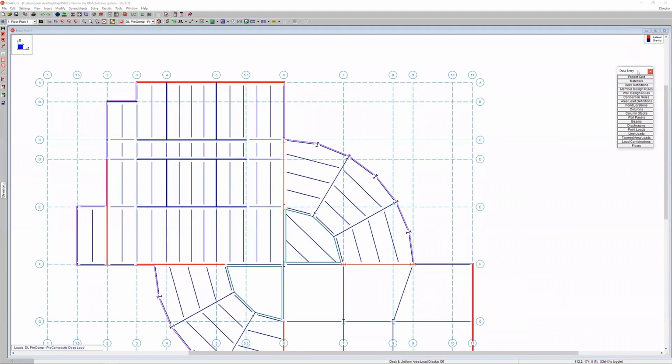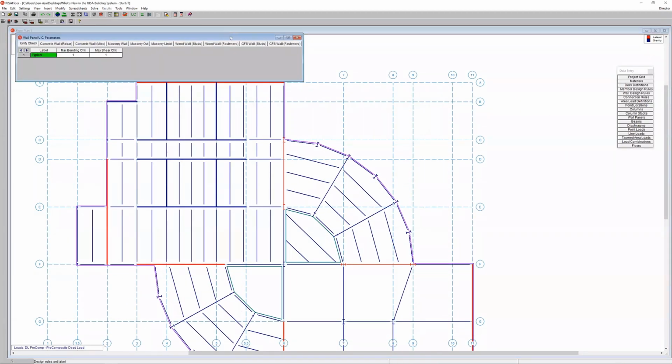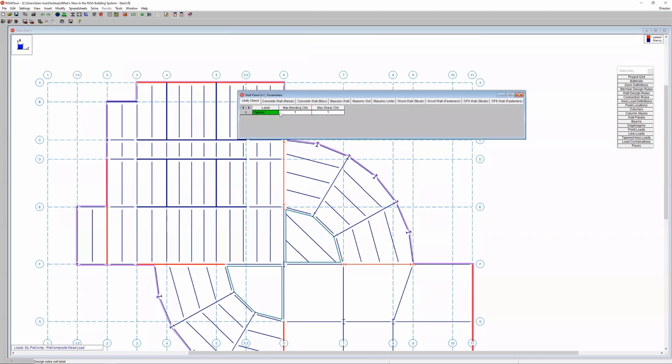The first thing I'm going to do is look at our wall design rules. Typically, we have very specific wall design rules for each individual material. If we look at CFS wall studs here, we can define our top plate, our sill plate, our stud spacing, and then our header. That's the information for the bulk of the wall.